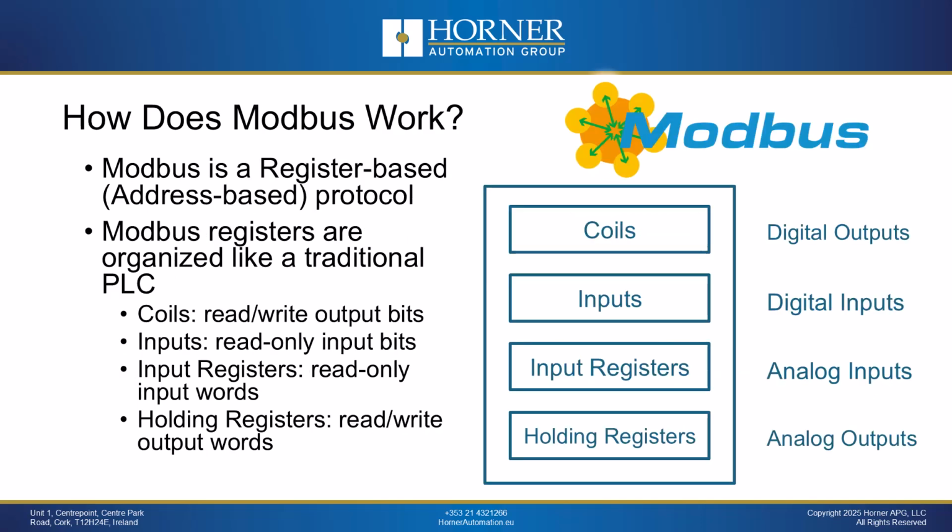Modbus is a register-based or address-based protocol, so it's not an object-based protocol, like a lot of the newer, more modern protocols. However, it still works extremely well for interfacing with devices such as drives. As Modbus is a register-based protocol, the registers are organized like a traditional PLC. There are 4 different types of Modbus registers. Coils emulate digital output bits, inputs emulate digital input bits, input registers emulate analog inputs or read-only inputs, and holding registers emulate analog outputs or internal PLC registers.